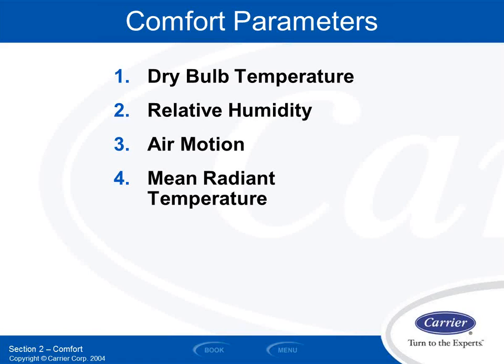The radiant temperature is yet a third temperature in a space that will influence your comfort, and it's not directly related to the dry bulb temperature. I mean, the radiant temperature will change the dry bulb temperature, but it's not the same thing. So by that, let's take an example.